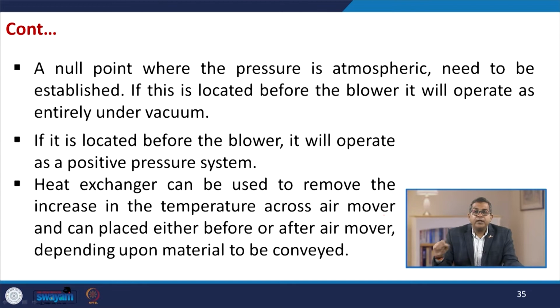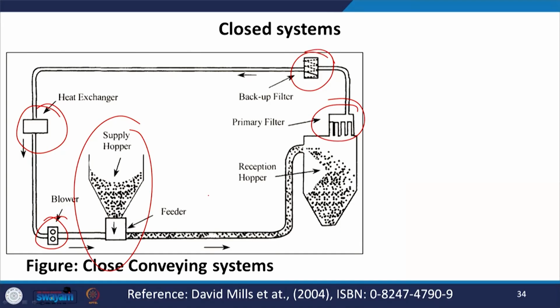Now, a null point where the pressure is atmospheric needs to be established. If it is located before the blower, it will operate as entirely under vacuum. If it is located after the blower, it will operate as a positive pressure system. Here you see in this figure.